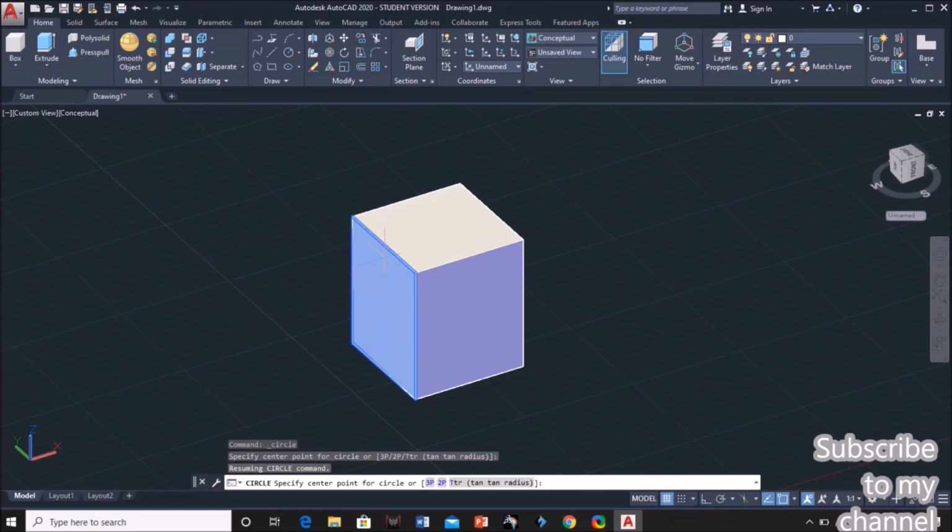For that, just go to the midpoint on this edge, move the cursor, and again come here and get the midpoint snap point and move the cursor in this direction. At the intersection of these two points you will get the center point. So click that center point and give some radius. I am giving the radius as 20 and click on enter. So the circle has been drawn on that face.